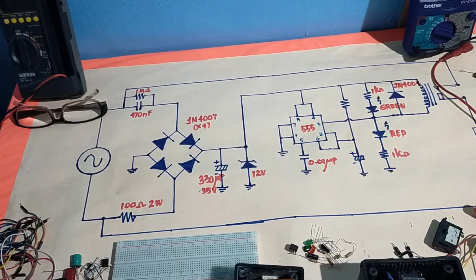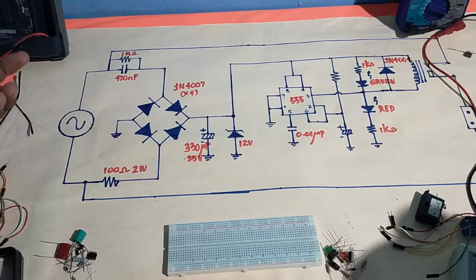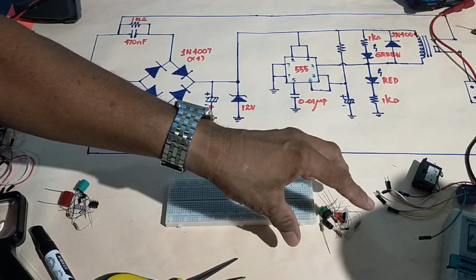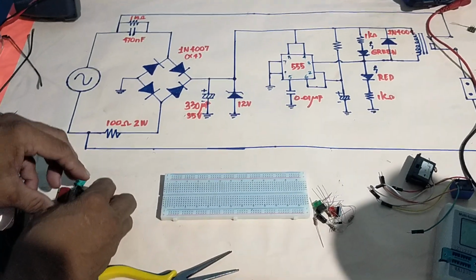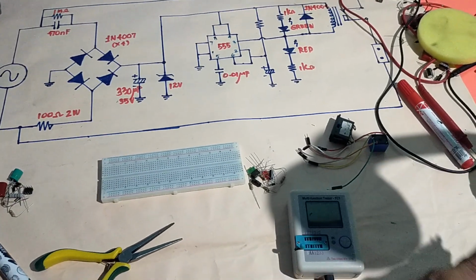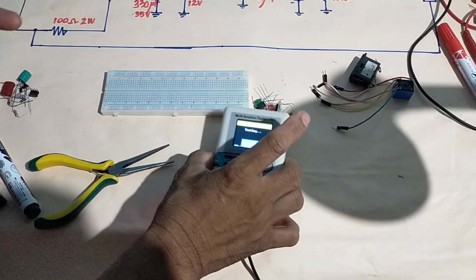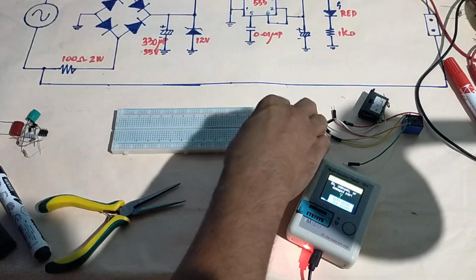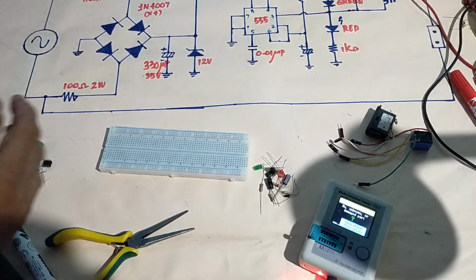Okay, let us start now the activity. We are going to assemble the various components here on this breadboard. But before you install these components on the breadboard, it is a proper procedure for us to first check the functionality of the components, whether the components are still good or bad. Although the components are still new because they are newly purchased from the electronics hardware.